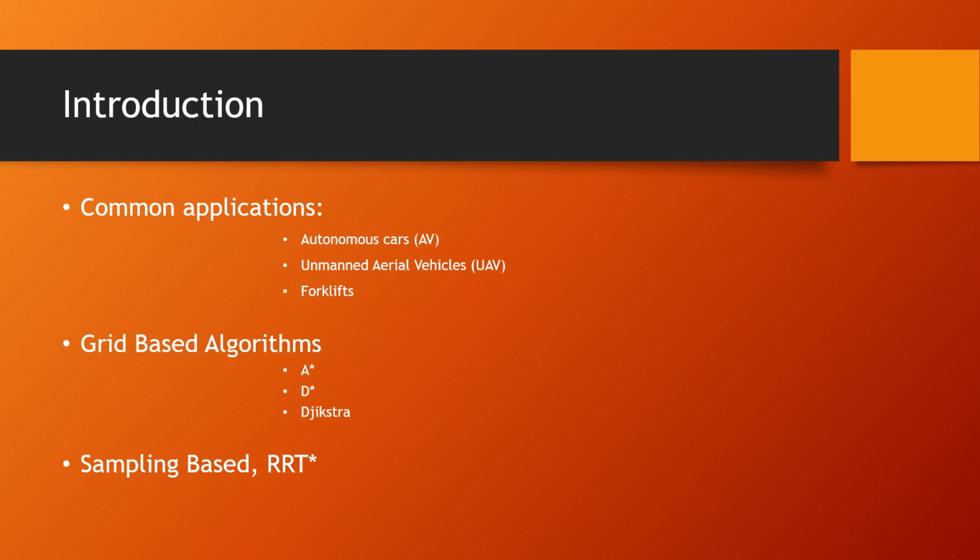At first, initial planners included roadmap, potential fields, and cell decomposition techniques. Talking about common grid search based methods, we have A star, D star, and others, which are complete but their shortcoming is that they are computationally expensive. There are others such as particle swarm optimization, bacterial foraging, and bio-inspired neural networks, but they are highly sensitive to search space size.